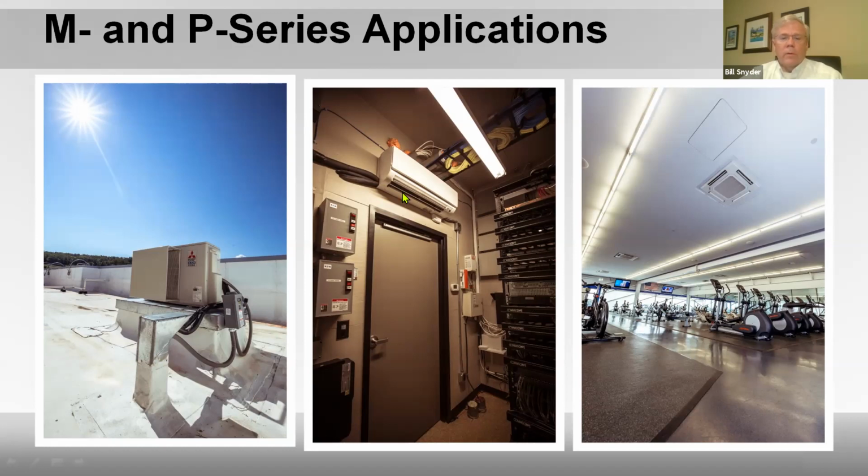They mounted this above the door, so if it does drip, if the condensate pan plugs up or starts to come down here, it'll leave a puddle in front of the door and it won't be dripping on any electronic components. Good application. So a ceiling type cassette above this would probably not be the best application. If you're putting a ceiling cassette in, make sure it's like up here where if it does fail and does drip, it won't land on any components.